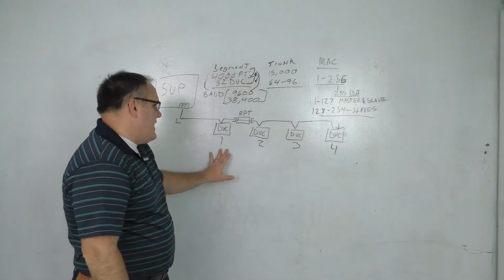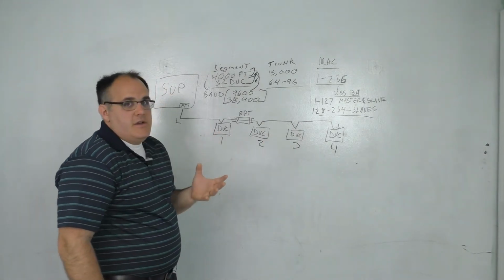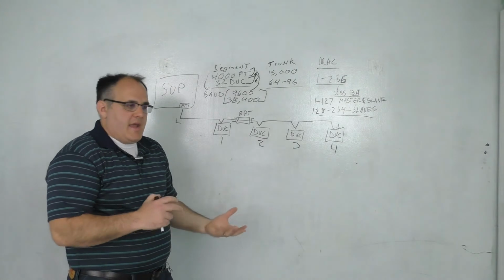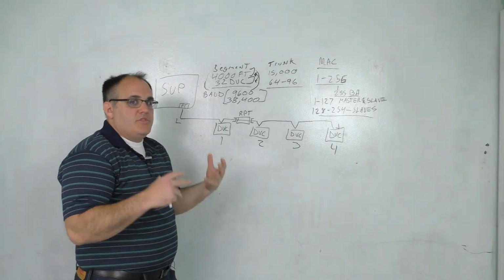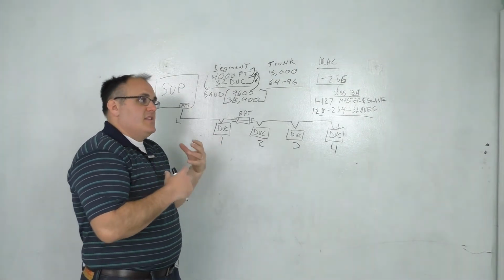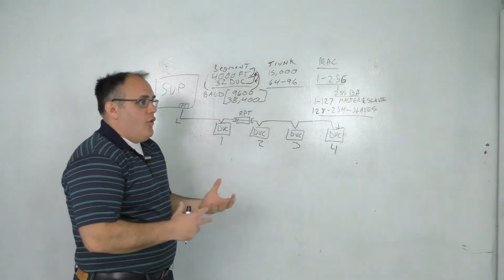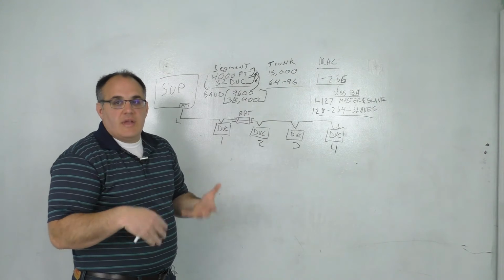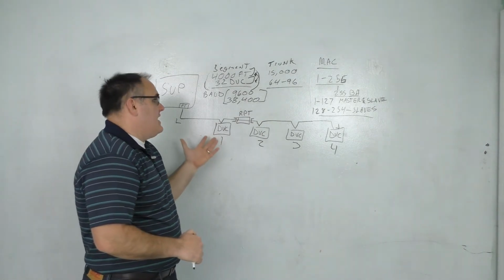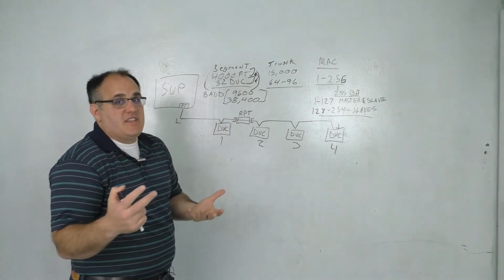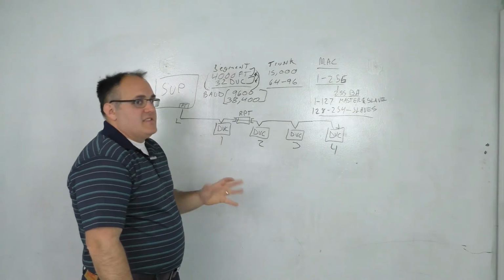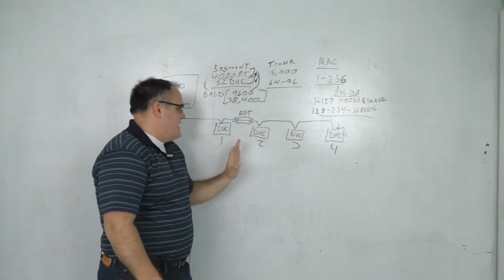And the reason why is how the token works. Whereas Ethernet frames are the data unit, the message type, for layer 2 Ethernet communication, for BACnet MSTP specifically, the data type is the token. And what happens is this.